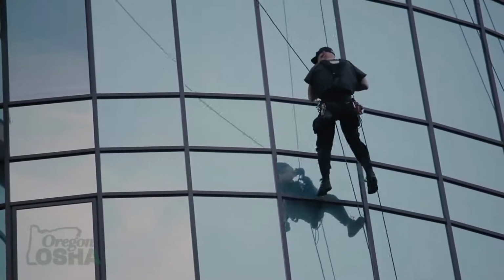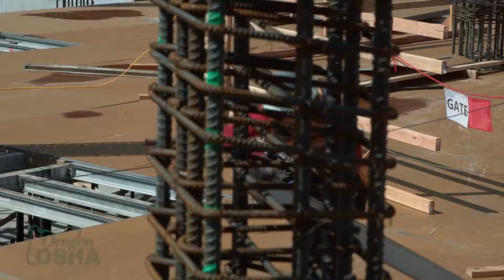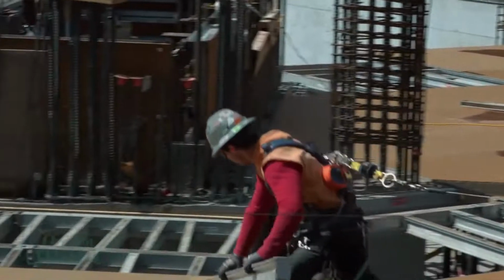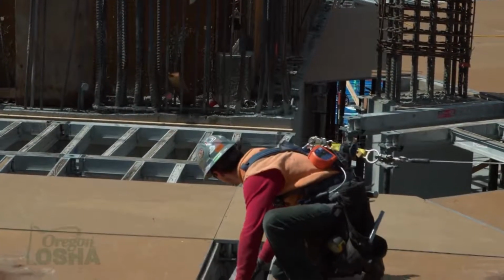If they've incorporated a personal fall arrest system, they shall be trained in the proper use, care, and inspection of either the horizontal lifeline, the anchorages, the harness, the connecting device with lanyard or retractable or other. Training is really critical for portable ladders, for rope descent systems, rope access systems, travel restraint systems, personal fall arrest systems, because each one of those systems has multiple pieces of equipment that must be assembled in the correct order, that have incompatibilities, certain ways that they can or cannot be hooked up.